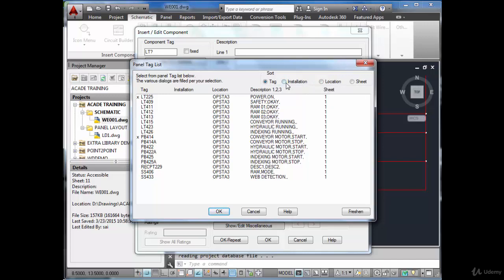If you provide this information there, that will help you for functions like this. Because if you have many locations, similar push buttons are used, similar CAD numbers are used in many drawings, you cannot identify. In fact, the sheet number is there, you can use this as well. So if the installation code is there, you can sort it installation wise, sheet wise. All these options are there, but right now we have only one sheet, so that is not creating any hurdle.